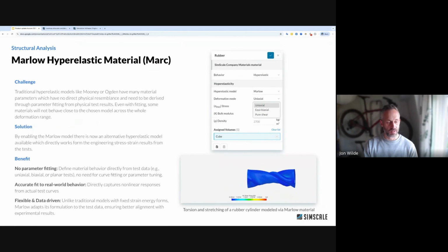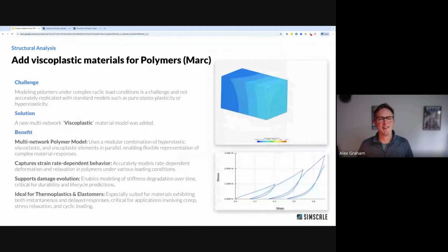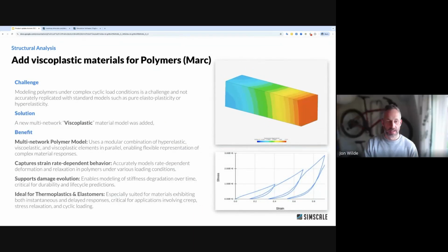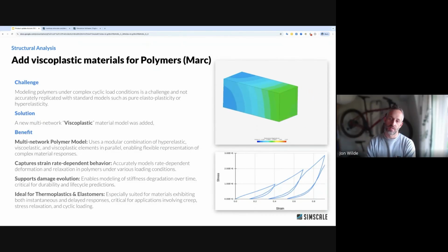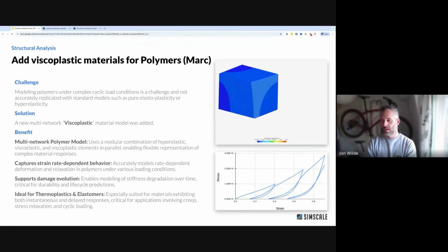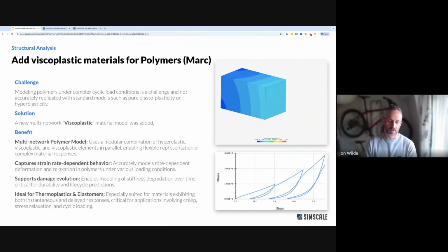Different to the door seal, right? Yeah. Indeed. And then I guess this gets a little bit more complicated too. We can now model viscoplastic materials. So the material properties can change depending on what happens over time. If you look at the stress strain graph at the bottom, what's happening is that the material is breaking down over time, and we can start to model creep, and we can model damage as cyclical loading takes place.